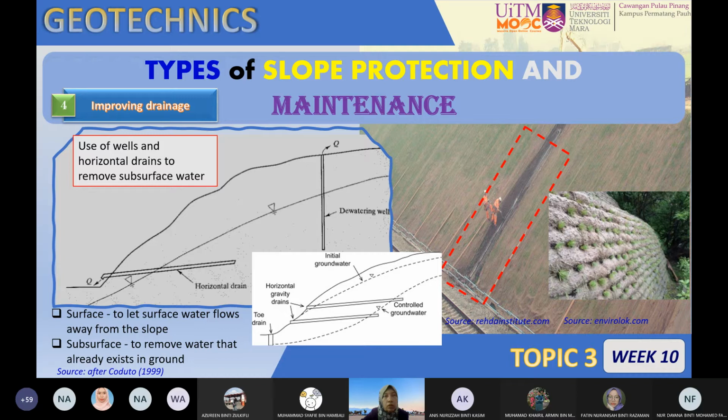Even if you only have one small drain or trench, just imagine the drainage is clogged by debris, so you stop water from flowing out. The consequence is that the area will be flooded by the water. The same goes for the slope. If you do not design proper drainage, you will see some water flowing out, and then the soil becomes fully saturated, and slowly the water will fill.